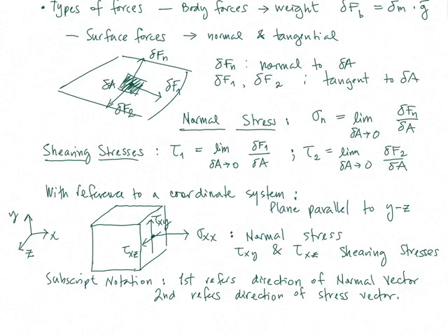We also need a sign convention, and we use the following sign convention. We define the positive direction for the stress as the positive coordinate direction on the surface for which the outward normal is in the positive coordinate direction. Now, I'm going to draw in the next page a little sketch about this to explain it.